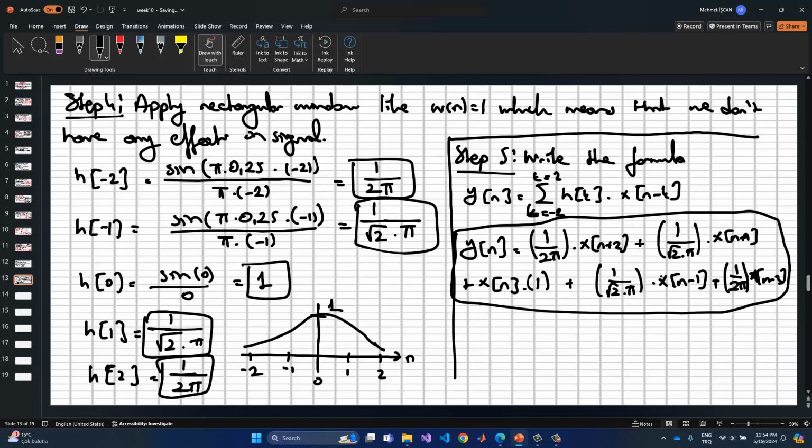Remember that if we increase n, we lose the beginning and end points at the rate of n divided by 2. Right? Because if we increase the FIR filter up to 50 values, we have x[n+50] to x[n-50], which means that we cut the first 50 samples of the signal in here.